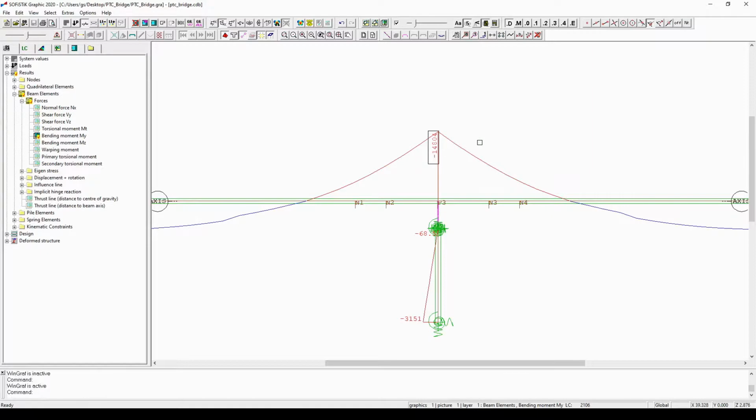As you might realize by now, sometimes it is not so easy to assess or to obtain the necessary amount of reinforcement. In some cases like this, you might need to fine-tune your model by adding some extra tendons, changing the geometry of the tendon, or using some extra controlling option in the design procedure.